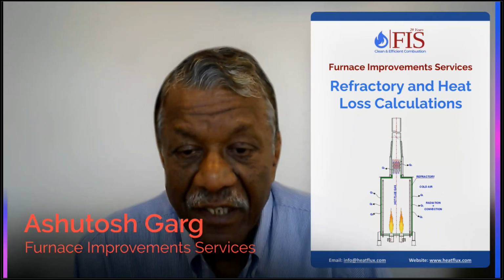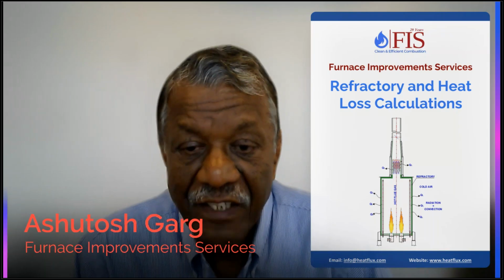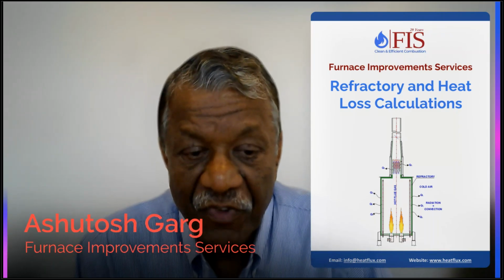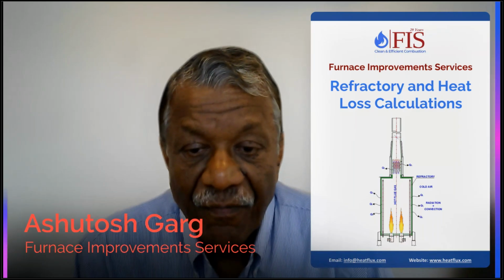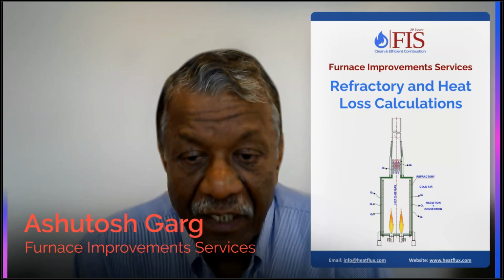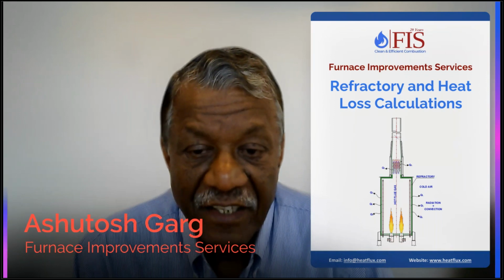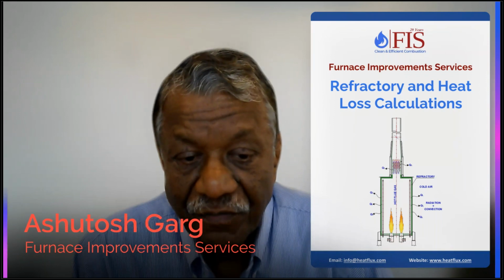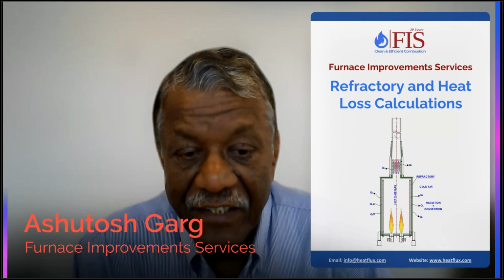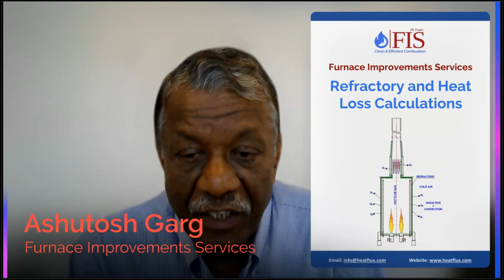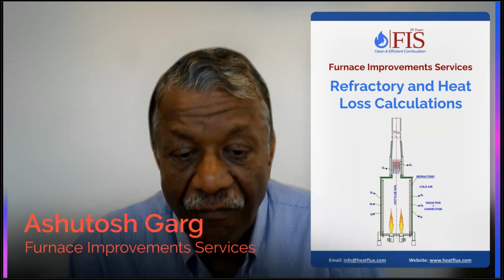You look at the breaching, you look at the stack, it has refractory. You look at the hot flue gas ducts, cold flue gas ducts. Almost every piece which is dealing with high temperature has refractory lining, including burners. So refractory is a very important component and we will be covering it today.